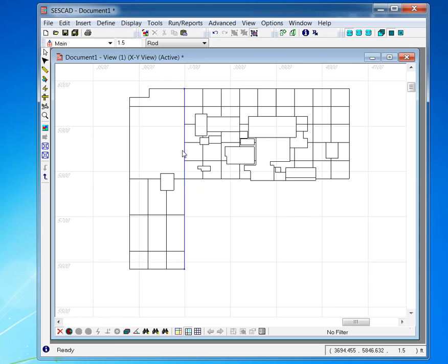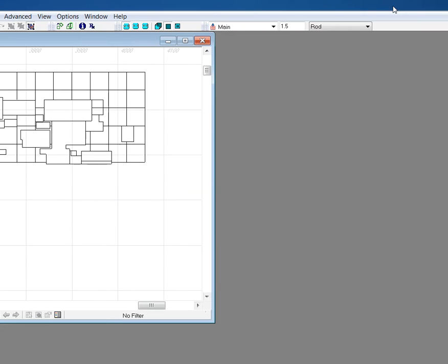I will show why the color is different, but for now, the first thing you want to do is make sure this is underground before doing anything, because usually when you import or insert from an AutoCAD file like DXF, the software doesn't recognize the elevation. To do that, there is a very simple method that you can follow.